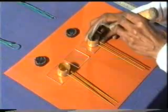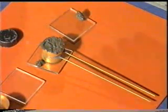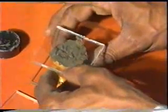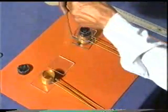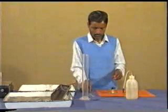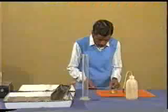Fill the Le Chatelier's mold lying on the glass plate with the prepared cement paste. Now cover the filled up mold with another glass plate and place a 50-gram weight on this plate. Tie up the whole assembly with a thread. Now measure the distance between the tips of the indicators, which is 13 millimeter in this case.